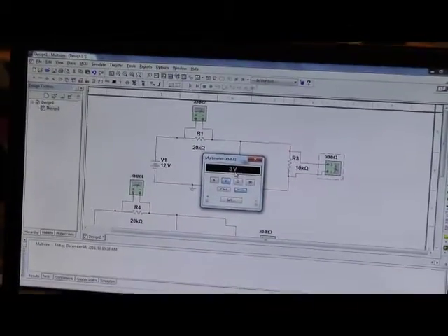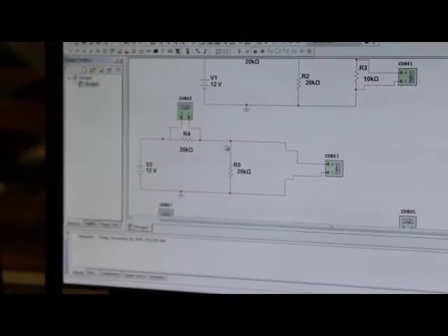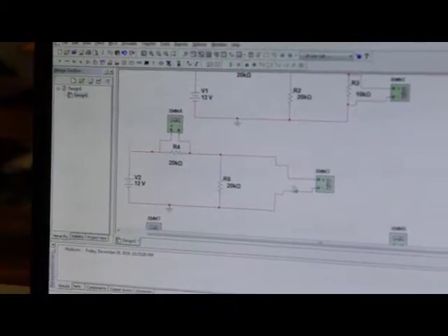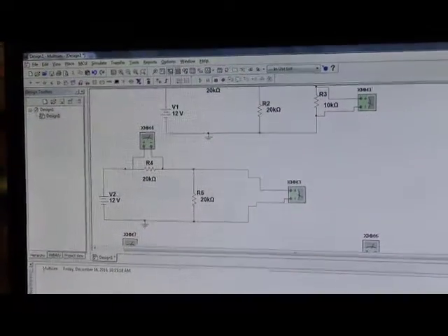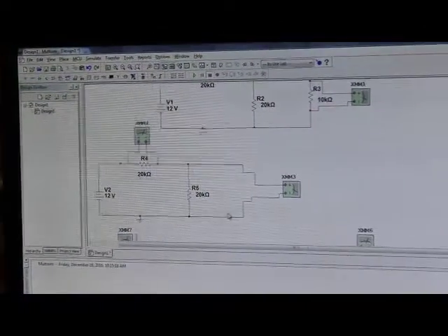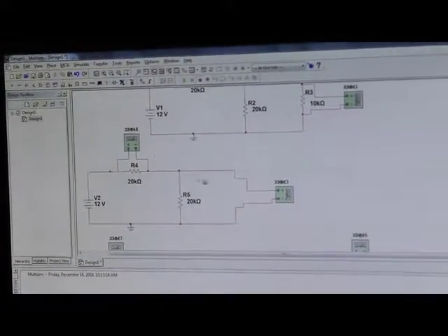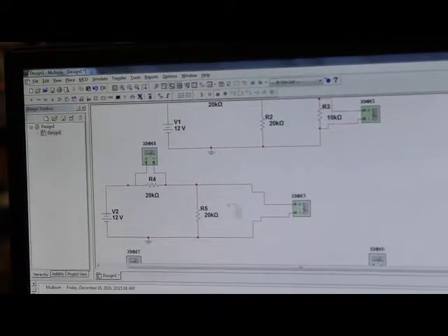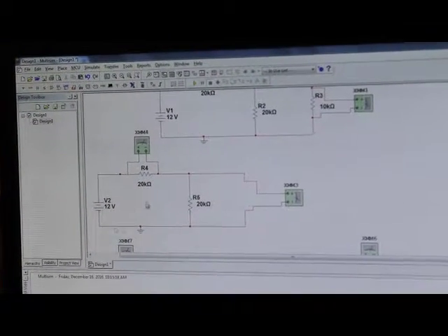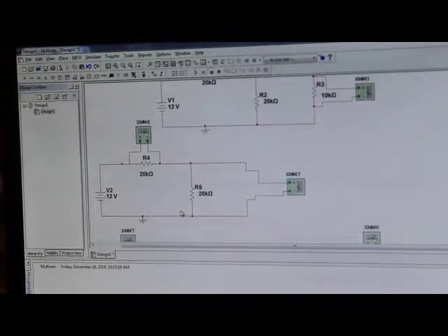3 volts. Let's remove the load and move to the next circuit. In here, as you can see, we already removed the R3 and we only have 2 resistors and a much simpler circuit. So what we're going to do now is find the Thevenin voltage. In order to find it, we must assume that the current never flows to the R3, and therefore this circuit is but a mere series circuit.